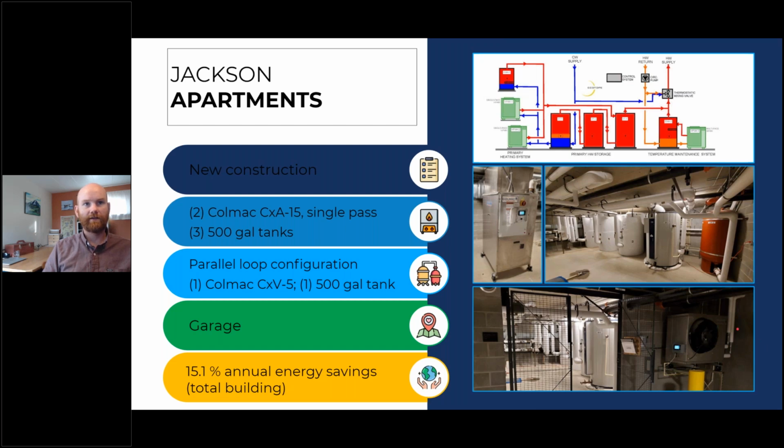So looking at this a little bit further, we have our conceptual schematic up top here. We have two primary heat pump water heaters and a backup electric resistance water heater, as the owner wanted a backup non-heat pump water heating system serving this building as well. And then we have three primary storage tanks, and we learned in session 1 that we can either configure those in a series arrangement or parallel. At this project, we are arranging those in series.